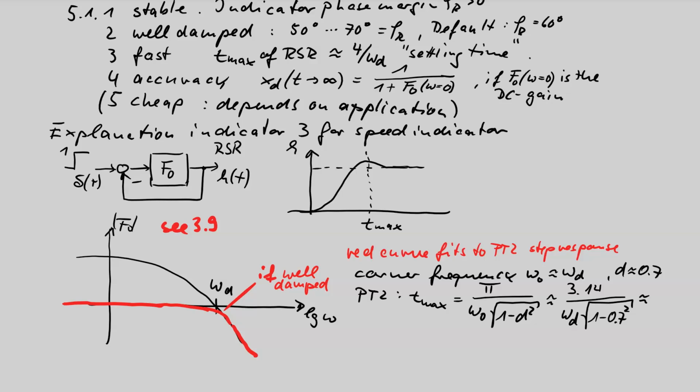Now I have to correct myself, not 0.7. If I calculate with a phase margin value of 60 degrees, this can be converted in a second order system into a damping factor of 0.61, with an equation you can find on page 33. There you can find for second order closed loop systems a very clear ratio between phase margin and damping factor.